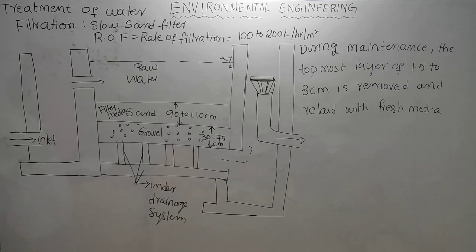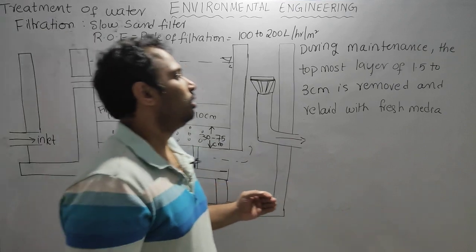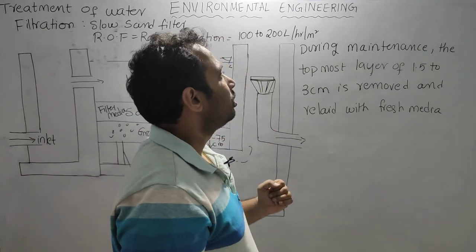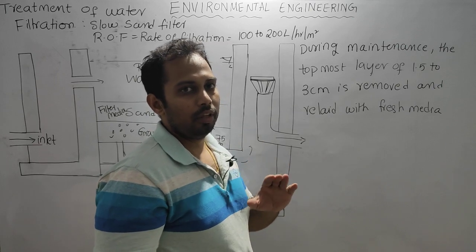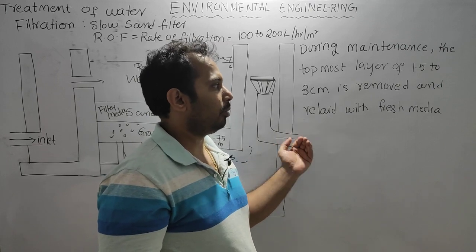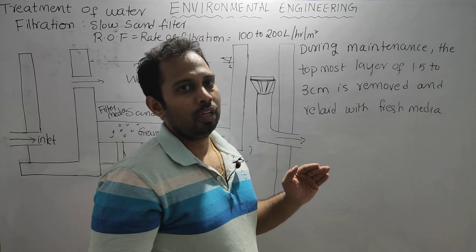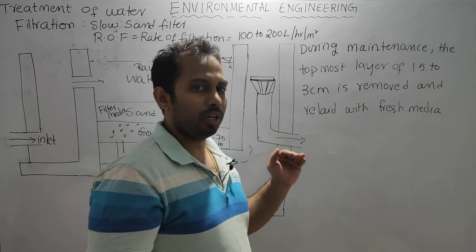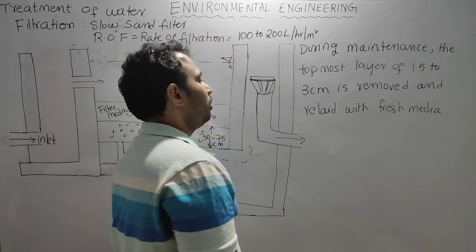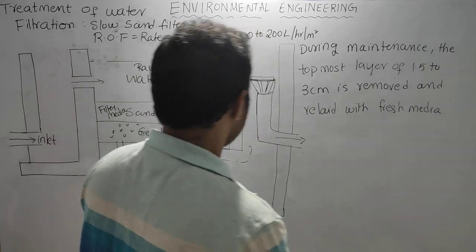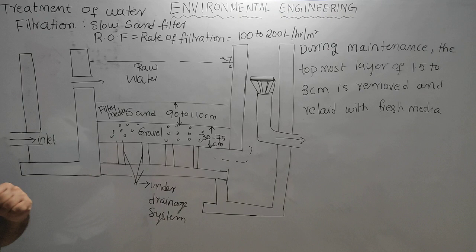After resumption, once the maintenance is over, we don't consider the water coming out after the removal of the filter media as filtered water. After the formation of the Schmutzdecke layer again, we don't consider the water as filtered water until then. After that we do it.